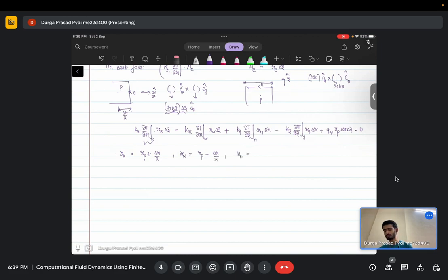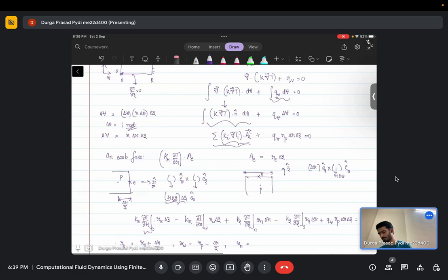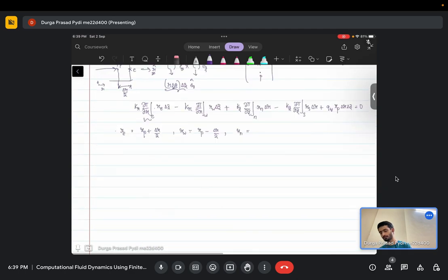R north is, if you are on this P cell, since we are considering a uniform grid everywhere, all of these face centers and cell centroids will lie along the same line, and this is my R axis. So RP and RN will be equal, and your R south face is also equal to RP, since all north face and cell centroids will lie on the same line.